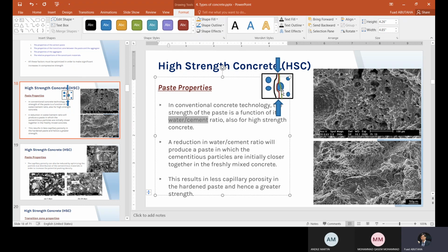But the strength of the aggregate today, if you leave it for 1 month or 2 months, is the same. It doesn't increase over time, inside the concrete or outside the concrete. So the strength of the aggregate has nothing to do with the development of strength. It is the same over time and doesn't change.